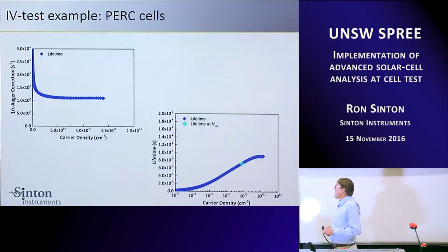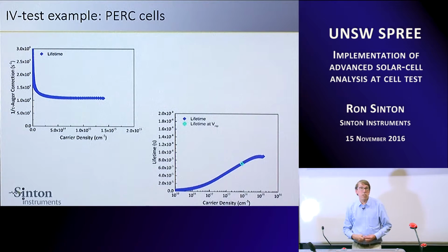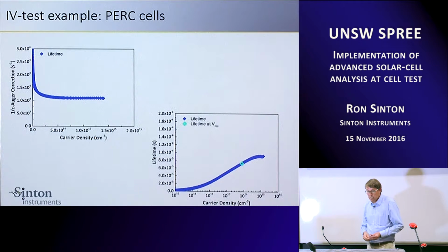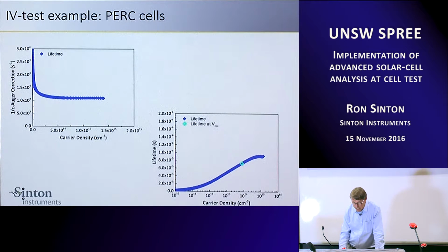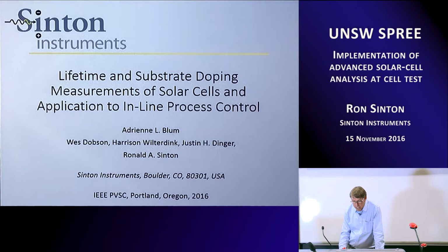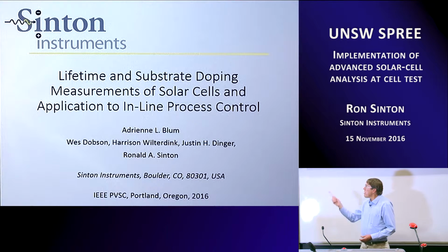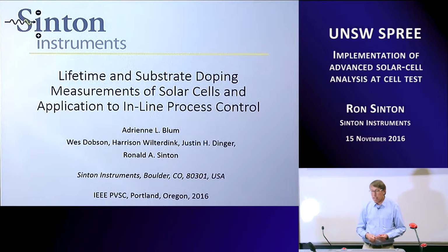with precision and uniquely. So you get this rather flat injection dependence, and then you have a very low lifetime at low carrier density. And this is typical for any p-type material because of the boron-oxygen defect or boron-iron or many other reasons. And so we actually did a study on this, and it was presented at the IEEE by Adrian Blum. And I'll show some slides for this.